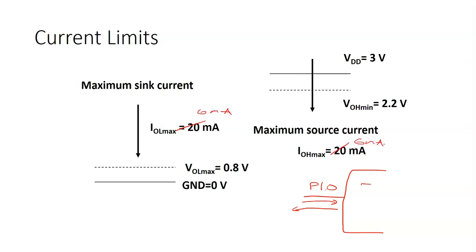A couple of the pins can support the higher 20 milliamp limit, but the majority of the pins, when you look this up in the data sheet, have a limit for sinking and sourcing current of 6 milliamps. There is also a constraint in total across all the pins, which you also have to be careful with. This is something around 50 to 100 milliamps.